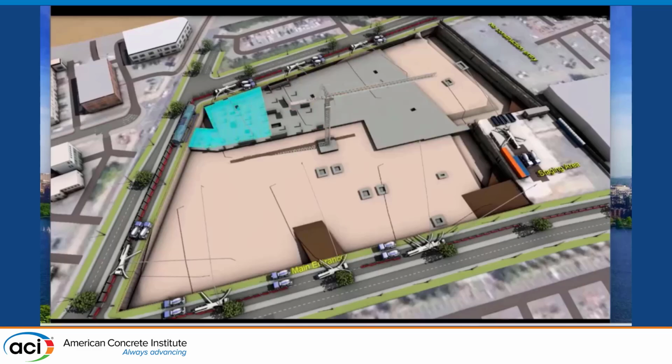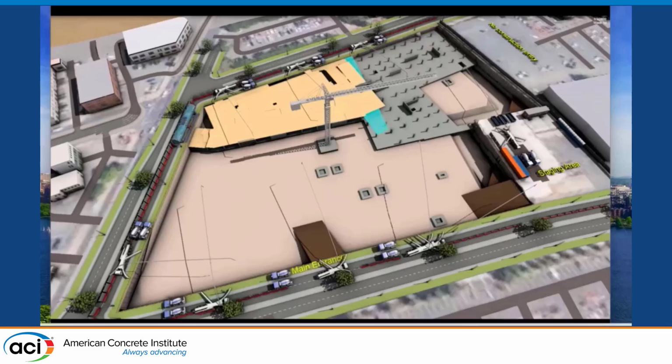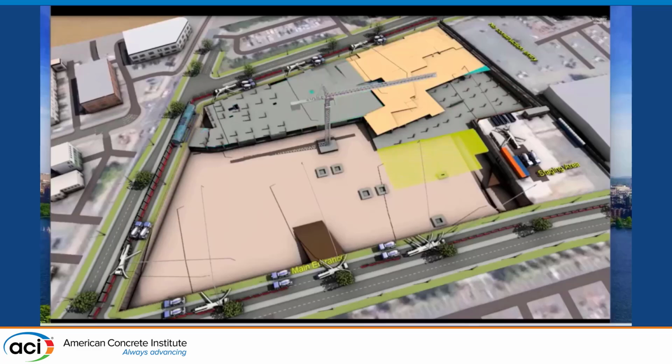So you can see the benefit of using a 4D plan is to visually tell the stakeholders the sequence and the site logistics plan. If you use this for, let's say, a lane closure permit, it's easier to get buy-in from the city.